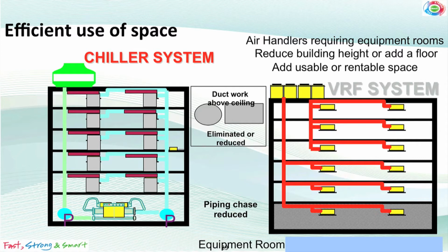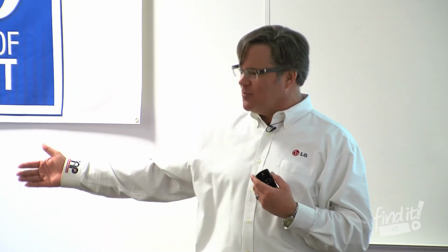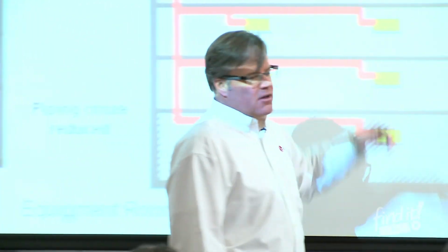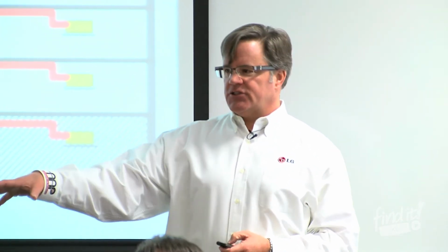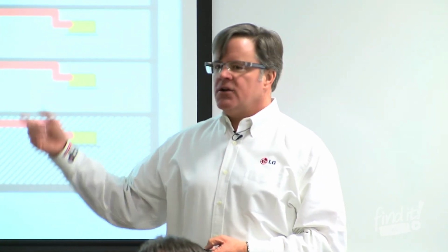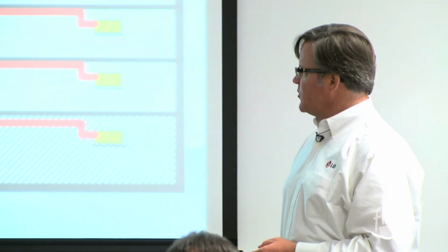A lot of schools look at this project because they end up getting a whole new section of storage space because they get to clear out their boilers and pumps and skids and all that stuff that's using up some of that usable space. So you now get to have some very usable space down here. So that is why, when you're using VRF or using refrigerant to transfer energy to the space versus water or air, people from even a building owner's side of it are looking at it from that perspective.